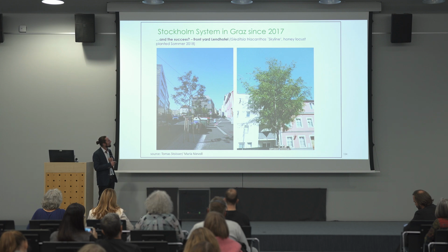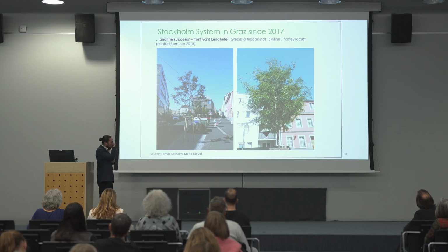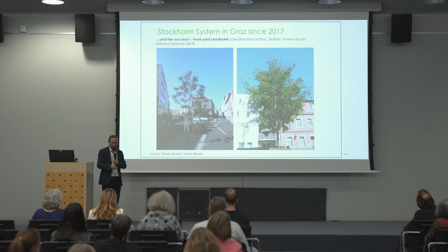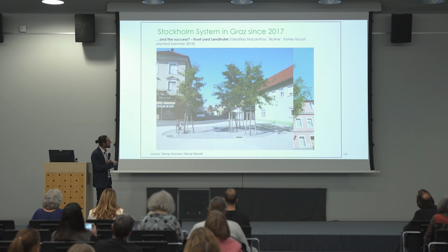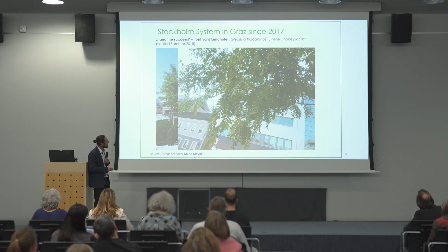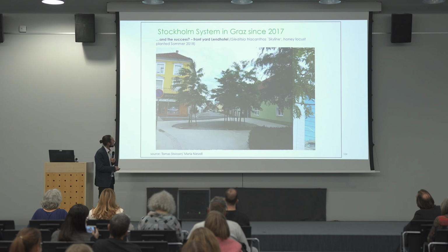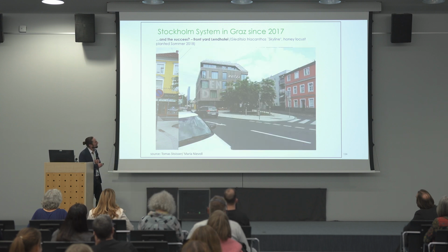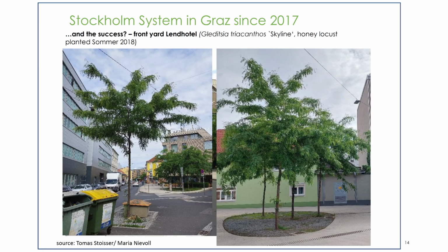And we also have one tree planted in a normal tree pit with normal tree substrate, planted at the same time. And there you see the difference on the left and on the right in the progress of the trees. This is 2 years after it's planted, a climate-adapted, really nice tree, the honey locust. And there you can see these really dark green branches, and this is a photo from this year, so they have quite a big crown and a really nice development. Over there, it's actually 1 crown now, as you want to have it for a place after 4 years.